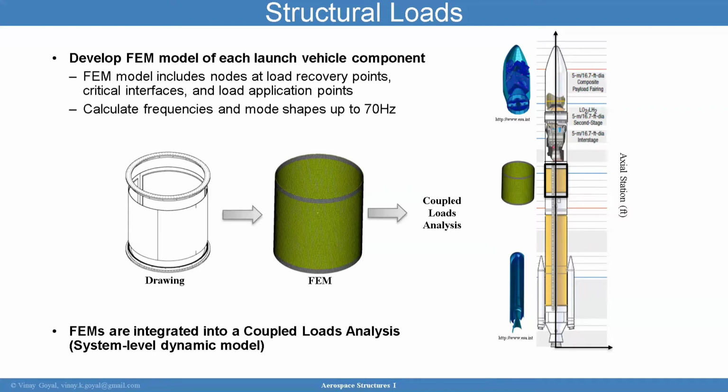And the idea then is to perform the coupled loads analysis, which is basically trying to determine how the spacecraft and the launch vehicle respond to each other when they're integrated together. Recall that the launch vehicle loads can be quite severe, and it could shake the spacecraft until it fails, or it could damage part of the launch vehicle.